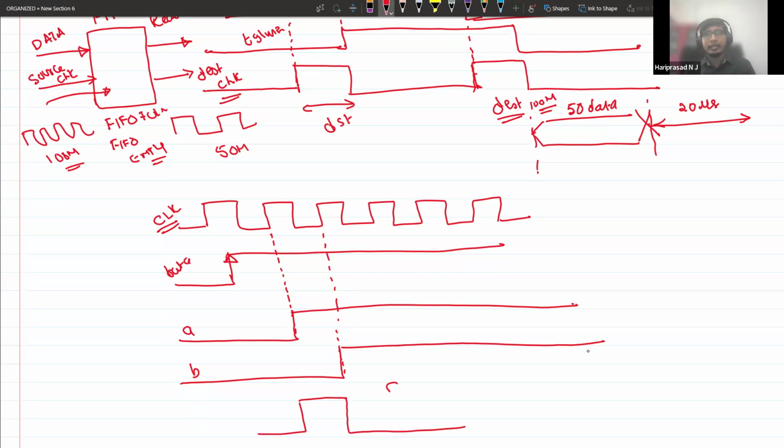It is A and not B, right? That will identify the positive edge. Wherever the positive edges are, I can identify them in the data. This positive edge detection is something you will see most of the time in your FPGA based designs. In the same way, you may have to detect the negative edge also. Similar conditions, but what modifications do I have to make? What is the condition for detecting the negative edge in the flip flop?